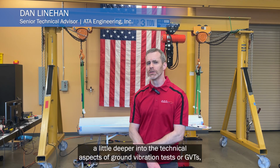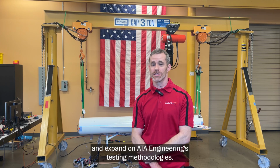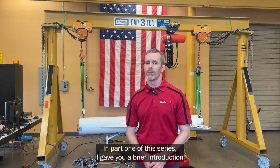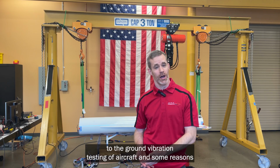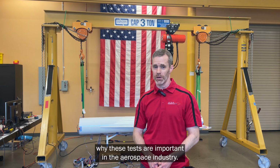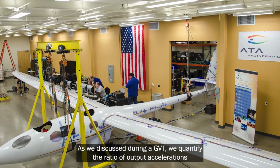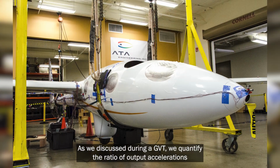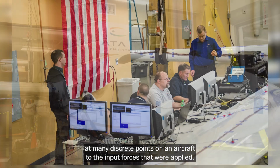Today we're going to delve a little deeper into the technical aspects of ground vibration tests, or GVTs, and expand on ATA Engineering's testing methodologies. In part 1 of this series, I gave you a brief introduction to the ground vibration testing of aircraft and some reasons why these tests are important in the aerospace industry. As we discussed, during a GVT, we quantify the ratio of output accelerations at many discrete points on an aircraft to the input forces that were applied.